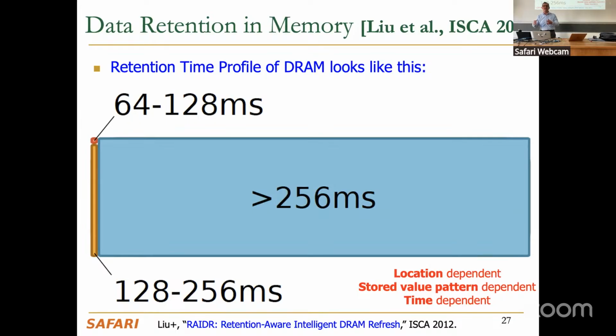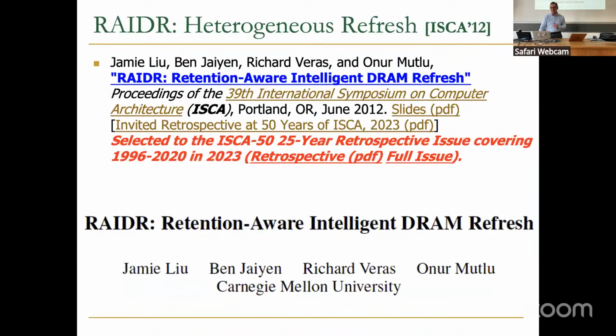When you test the retention time right now, the retention time may be 10 seconds. So that's good. That's a good cell, right? You don't need to refresh it that much. But if you keep doing that, you may be doing the wrong thing, because this cell's retention time may be dependent on random factors that you don't fully understand, called variable retention time. And if you test the retention time 2 days later, it may go down to 64 milliseconds. So you probably would do the wrong thing and lose data if you actually change the refresh rate for that type of cell. So there are a lot of interesting issues over here, and some of which we're going to cover in a later lecture.